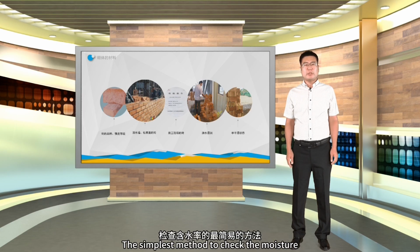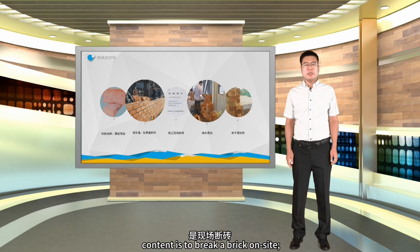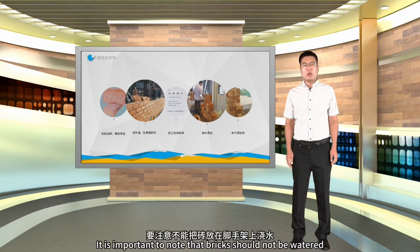The simplest method to check the moisture content is to break a brick on site. If the water penetration depth at brick cross-section reaches 15 to 20 mm, it is acceptable. It is important to note that bricks should not be watered while placed on scaffolding.